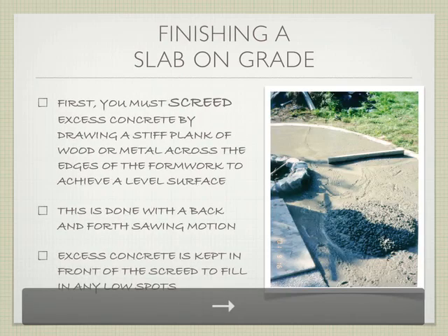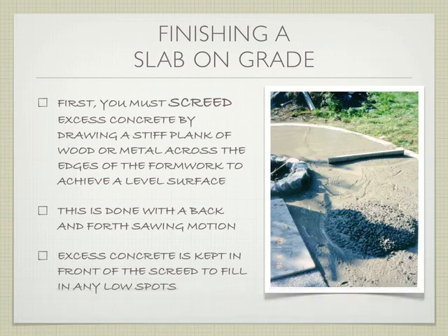After you have the concrete roughly in place, you're going to use a board, which is called a screed, and you're going to pull off the extra concrete. Chances are, when you were a little kid, you played around with this kind of stuff, or if you've ever baked, you've done the same kind of thing. Let's use the baking example for a second. You need to measure out how much flour and how much sugar go in your cookies or whatever you're baking. So you scoop up the flour, and then you take a knife and draw it across the surface of the flour to level it off and get it nice and flat. This is exactly what we do with concrete. Obviously, the concrete is full of things like rocks and whatever. It's not as fine as flour.